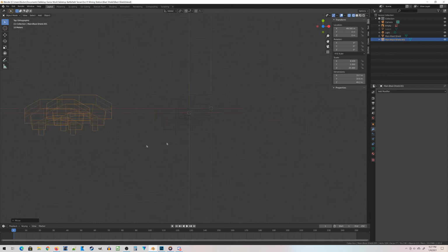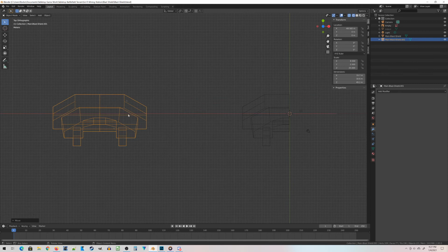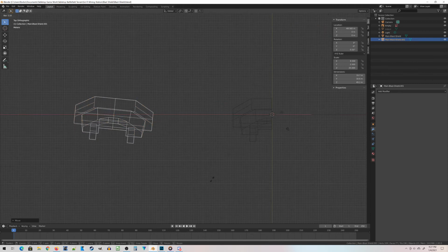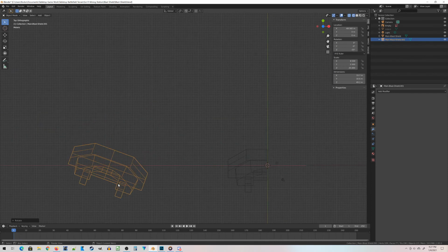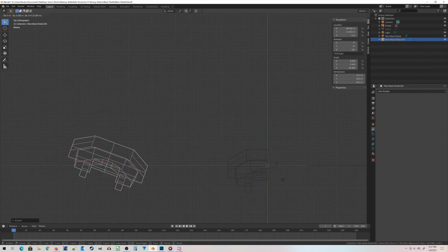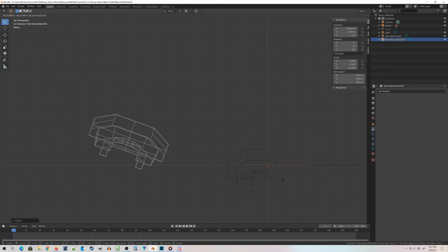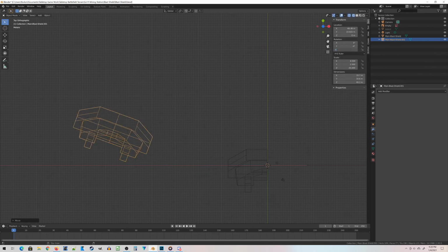So let's press 7 to jump to the top view. With our copy selected, I'm going to rotate that. Let's go 20 degrees. Not 20 degrees, minus 20 degrees because we're on this side. And then I want to scale, I want to put it somewhere around here. Once again, it looks like they're about 35 millimeters apart. In fact, I'm going to make this minus 30 degrees, so a little bit more.